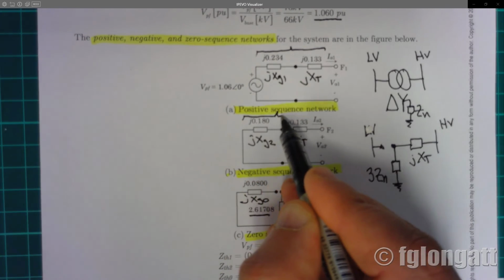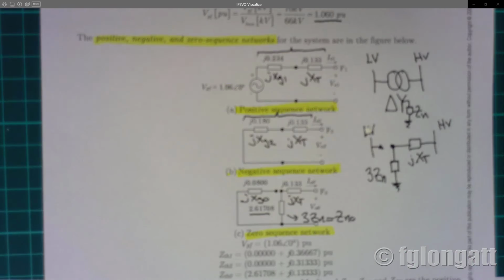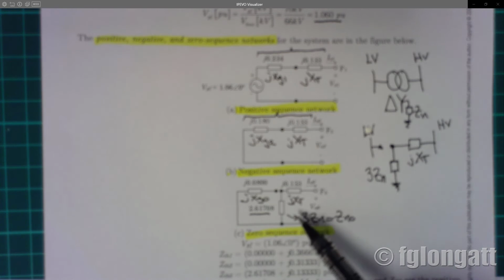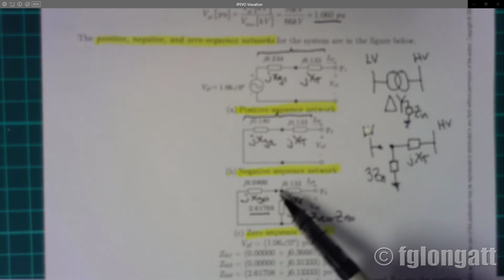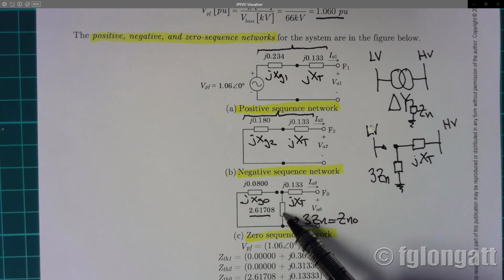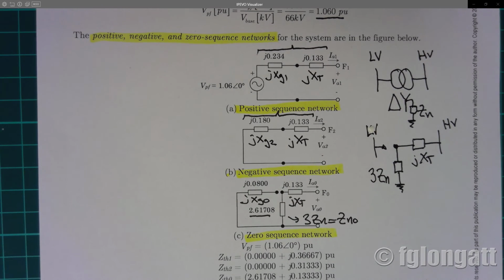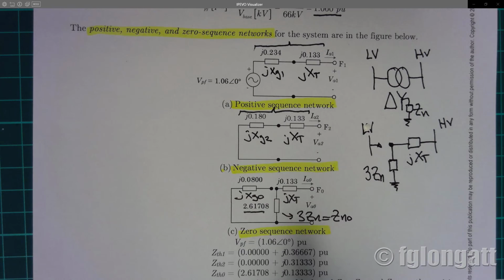I believe all of you can see this is the zero sequence connection, and there are two impedances here in series connection. We can apply the Thevenin theorem. We can solve the series connection, and that is extremely simple. All my students, they can do that. And this is the Thevenin impedance for the positive sequence, negative sequence, and zero sequence, okay?